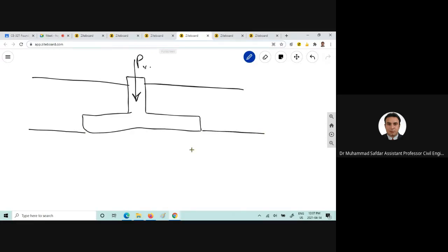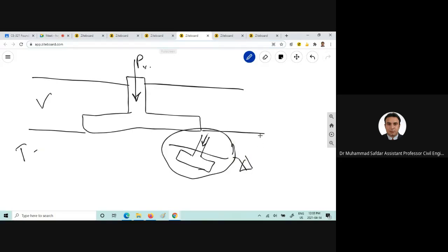So we are not dealing with, for example, a sloping ground or an inclined foundation as well. This is the case for Terzaghi's bearing capacity equation, and we will use different inclination factors when we discuss the Meyerhof bearing capacity equation.